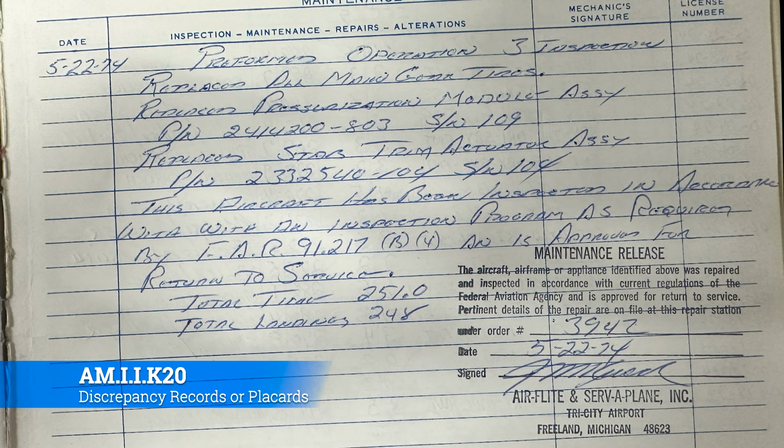Okay, and then number three, the signature and certificate number and the kind of certificate held by the person approving or disapproving for return to service the aircraft, airframe, aircraft engine, propeller, appliance, component part, and portions thereof. So essentially, you're going to put like Brandon Sanders, A&P, and then your number, which mine's got a lot of fours in it. 4044644, and then those brackets. And that's how you'll sign that off.